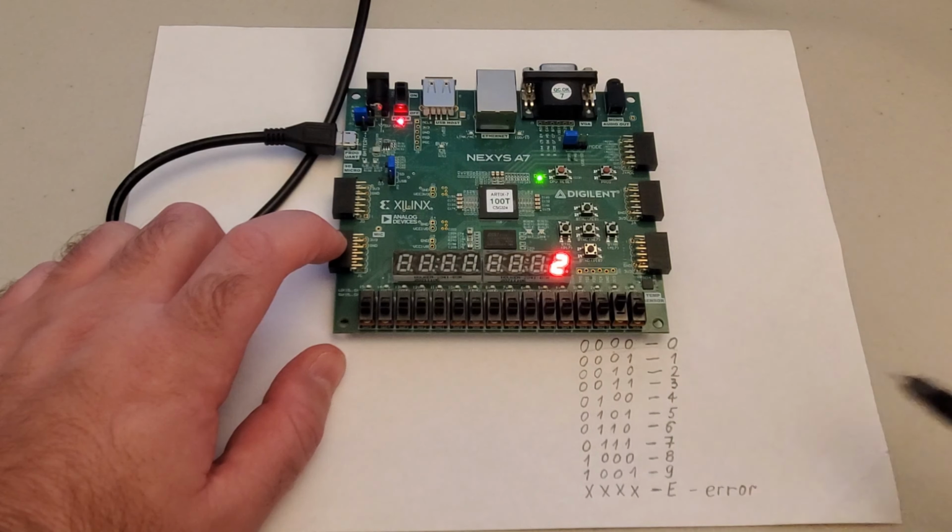A single 7-segment display has 7 LEDs. These LEDs are also referred to as cathodes. The LEDs are shown over here. We control the LEDs by sending 7-bit binary numbers. The LEDs are denoted by A, B, C, D, E, F, and G. We can group them in a single 7-bit binary number, A, B, C, D, E, F, G. To turn on a particular LED, we need to send a 0 bit.